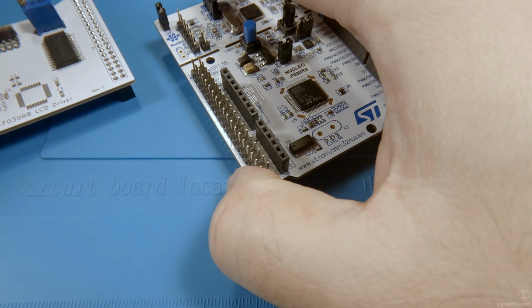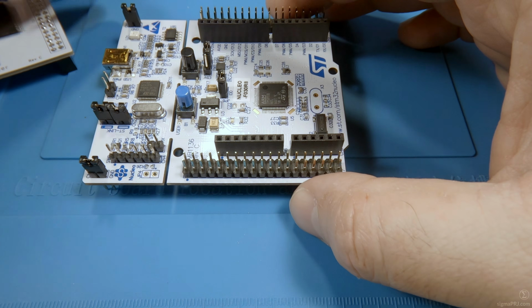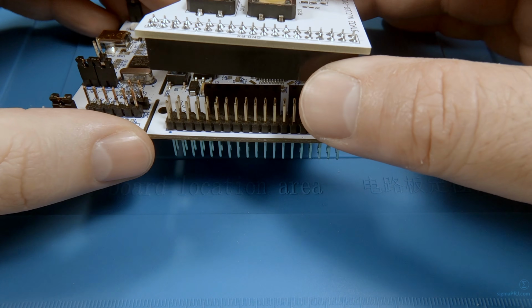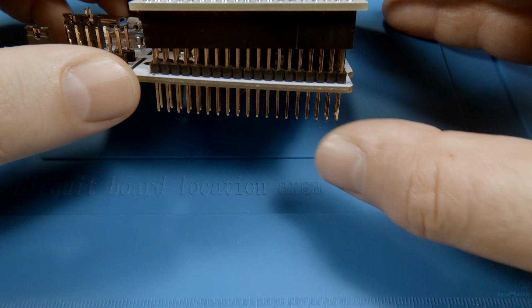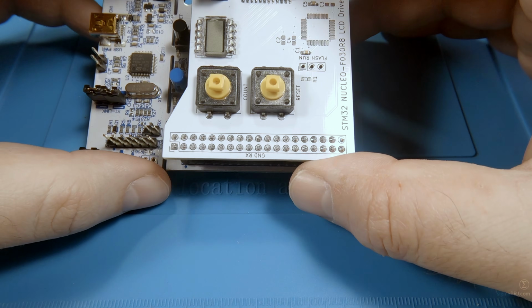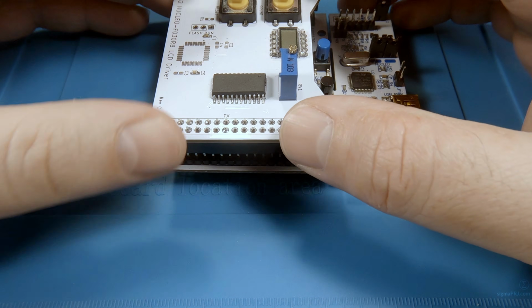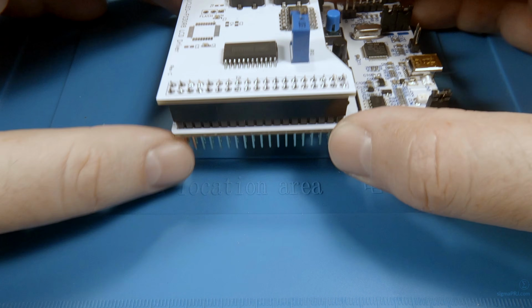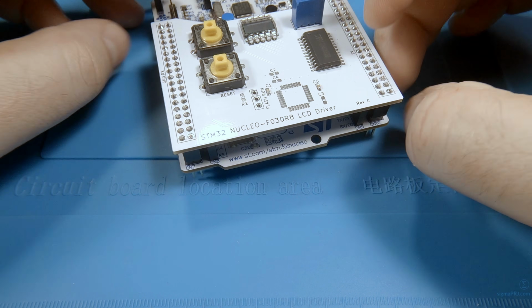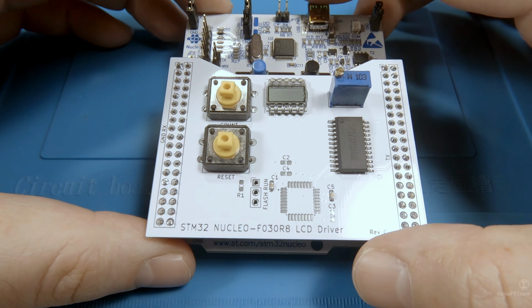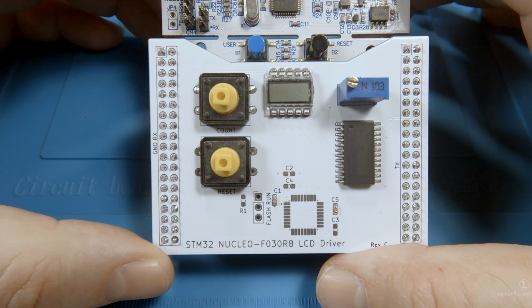Now we can plug the adapter PCB into our host board. This will give us the opportunity to debug everything using CubeIDE, where an SWD debug session can be established. So we could set breakpoints and look up actual variable values in runtime. And overall alignment looks quite good here.